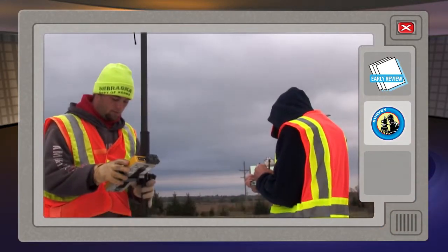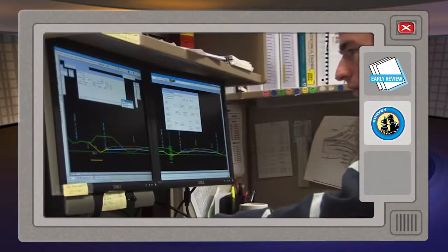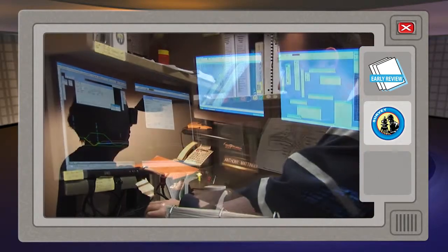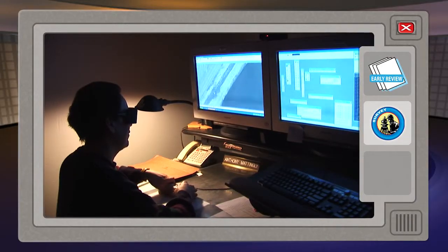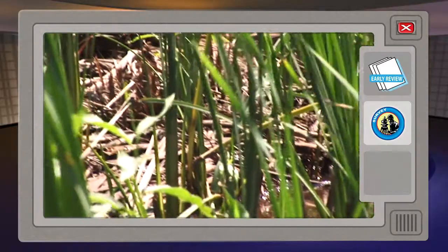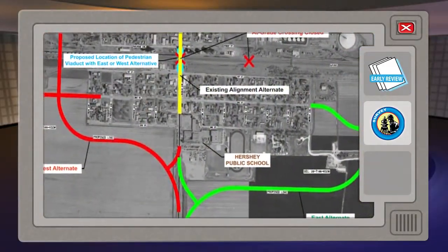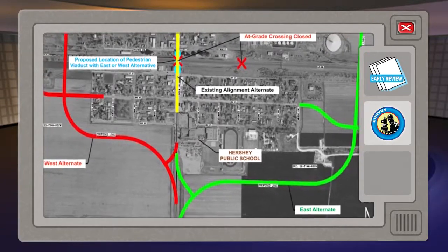Preliminary roadway design surveys are performed to provide topography and cross-sections of the proposed project area, as well as areas that may have a possibility of being impacted by the project, such as wetlands and endangered species habitats. The survey data is used to prepare simplified designs for project alternatives.